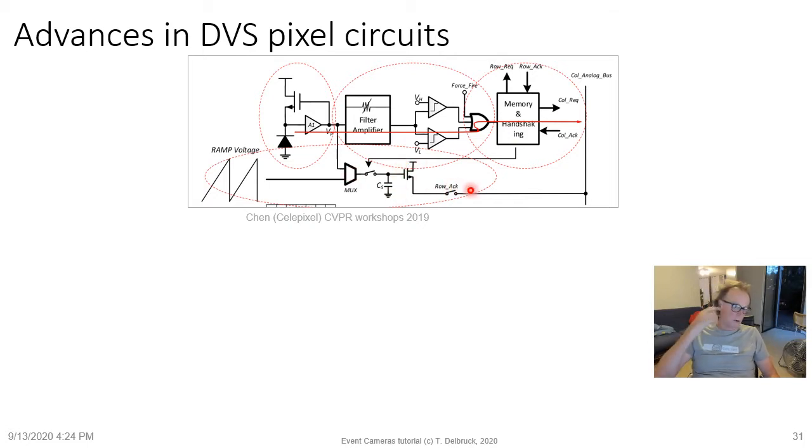Of course, this has problems of pixel-to-pixel mismatch. It means that each sensor needs to be calibrated at the pixel level, presumably with some kind of a gray screen, where the offsets are stored in firmware or something, or possibly it's some kind of very long time constant high pass filter. But in general, it basically looks almost like a DVS pixel. They claim it's not, verbally to me, but they never disclose the actual circuit, so it's not clear.